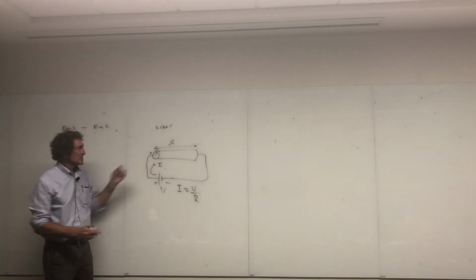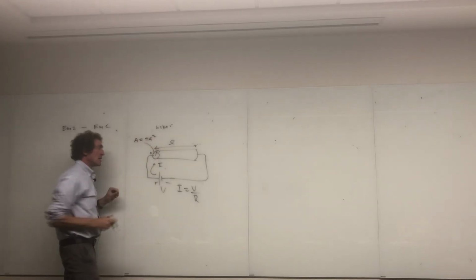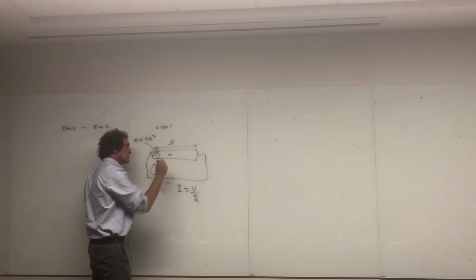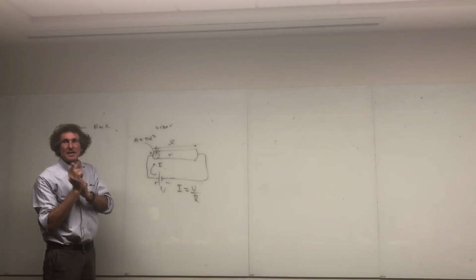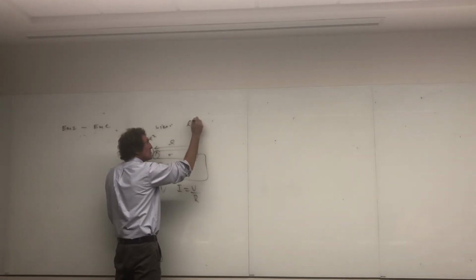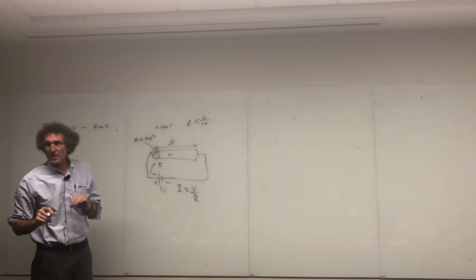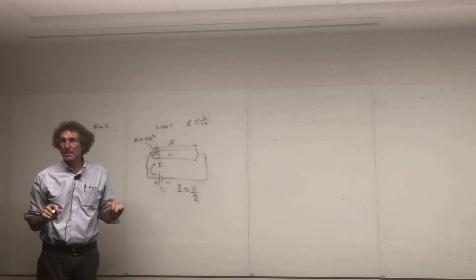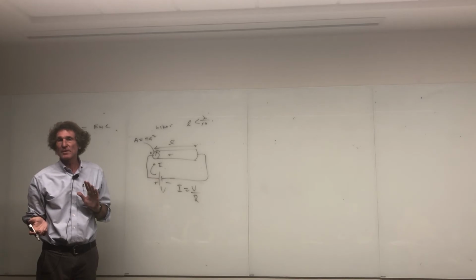This wire is long and skinny. It's got a cross-sectional area of pi a squared. And it has a conductivity sigma. So this is a good conducting wire. Now, one thing that is not stated explicitly in Wentworth's books, but L is always assumed less than lambda over 10, where this whole thing falls apart. Then you're dealing with a different type of radiating element. Lambda over 5 maybe, but typically lambda over 10. For short wires, this analysis works. It doesn't work for long wires, and you have to be aware of this if you're an engineer.